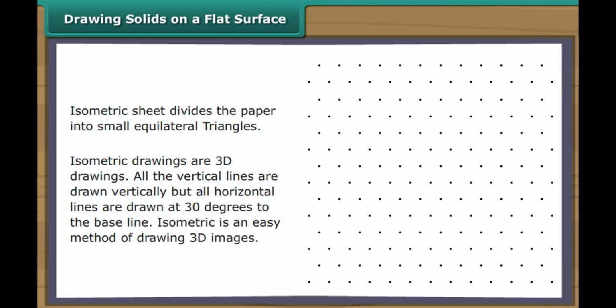Mark the front corner of the solid as A. Draw 3 units down, 3 units to the left, and 3 units to the right. Then, draw 3 units left from this last point. Draw a square for the top of the solid. Draw segments 3 units down from each vertex for the vertical edges. Connect the appropriate vertices using dashed lines for the hidden edges.